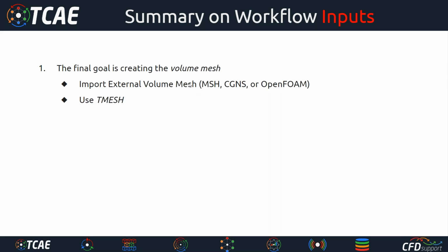So the automated meshing. This is what Radek has just described. You need to get the simulation-ready geometry, and that means that in some CAD system, we use Salome, but we do not push it too much. It's a little bit, I would say, specific. We use it because it's free, it's open source, and we can gladly recommend it to anyone who does not want to spend extra costs on additional CAD software. But you can use any other CAD system. The principle is always the same.